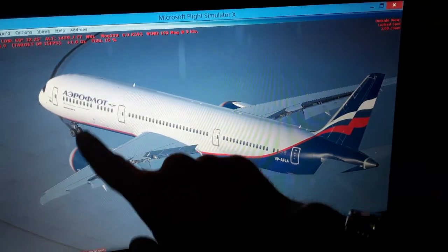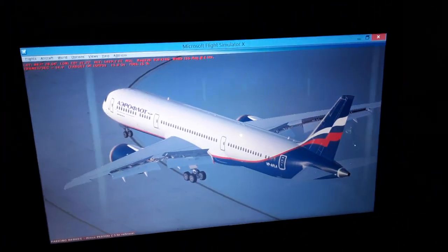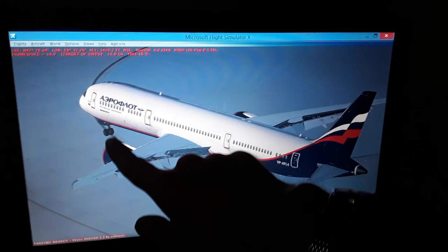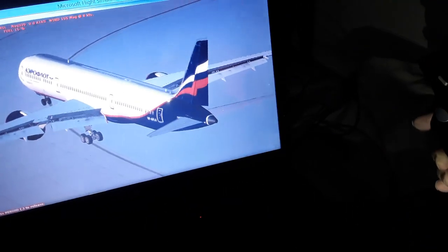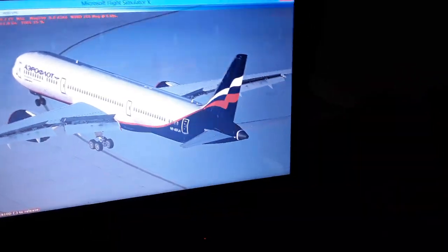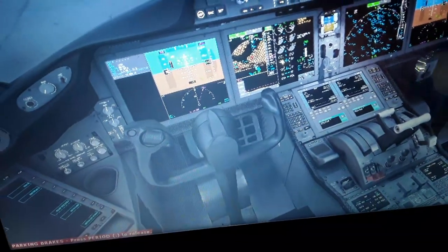In takeoff it decreases to 7.6 degrees because we have the rudder coming in, and then as we increase the takeoff speed to like 80 nautical miles per hour, it deactivates completely, and we have only the rudder aerodynamically effective for controlling the aircraft. So you can see we have the rudder pedals here for controlling the nose wheel steering of the aircraft.